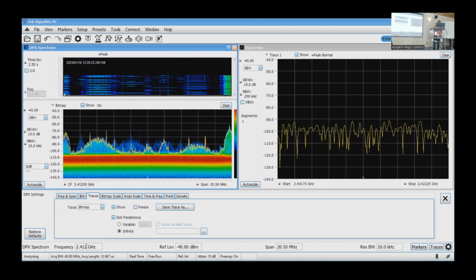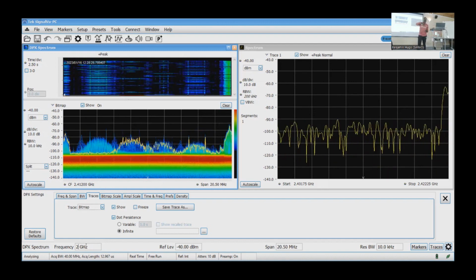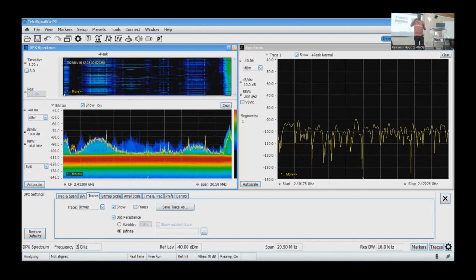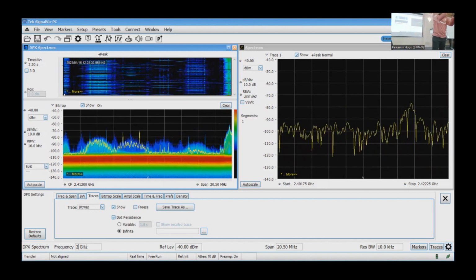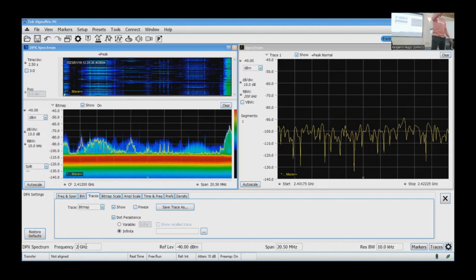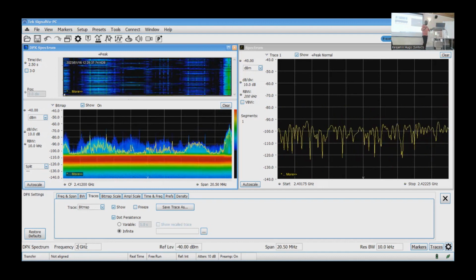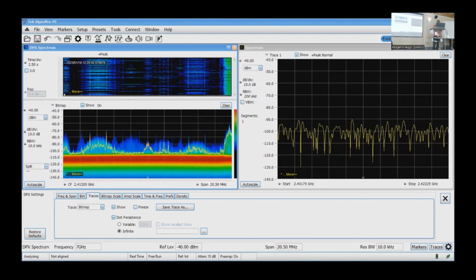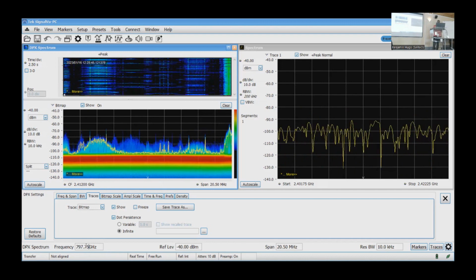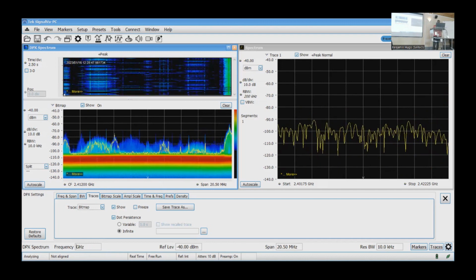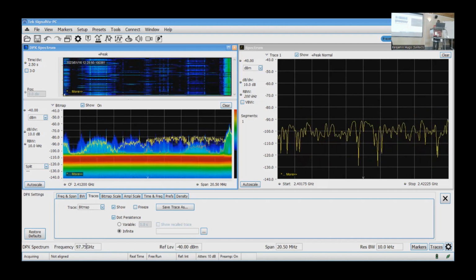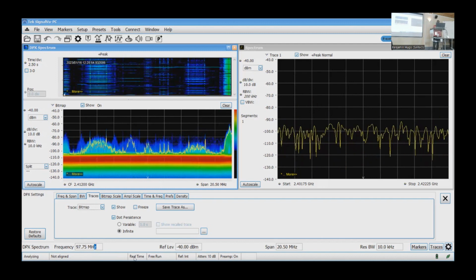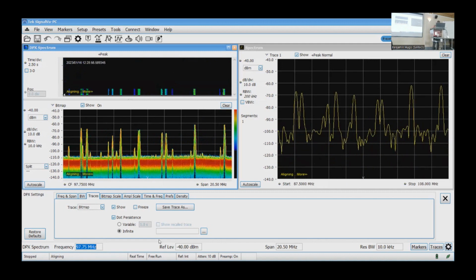So the middle frequency: 87 megahertz plus, if the span is that, you divide the span by 2. Remember, when you look at the bandwidth, it is with respect to the center frequency, so there's the positive side and the negative side. So that will be 10.25. You add that and you will get something like 97.75 megahertz, and you see what we picked already, right?